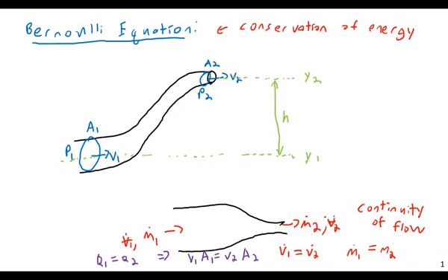But anyway, this conservation of volume isn't necessarily inherent to Bernoulli. The Bernoulli equation will apply regardless of whether the fluid is compressible or not. But the conservation of mass will always apply, and the conservation of volume will be a very useful tool that we can use as we also apply Bernoulli's equation. So again, I just wanted to justify why I'm saying that up here there will be a small cross-sectional area and a large velocity. Down here there will be a large cross-sectional area and a small velocity. And there will be the same amount of matter coming into the tube at this side as is leaving at this side.